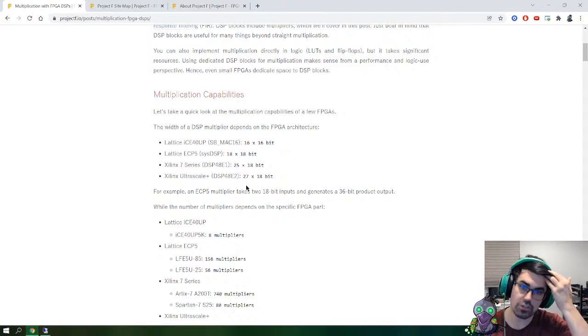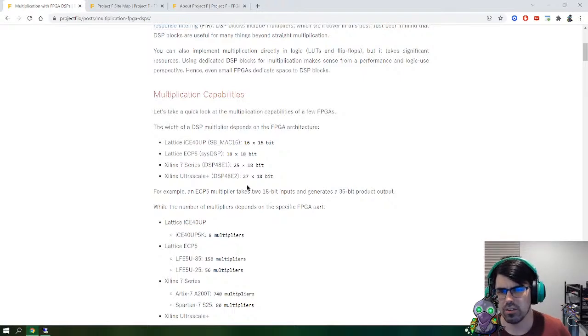Let's take a look at multiplication with different sizes. This is kind of interesting, because I was talking to a professor from Europe, I think, who was designing an 18-bit processor for the Series 7 FPGA, so it fit exactly with the DSPs. That's an idea: designing our HDL to match the capability of the FPGA. We can design a processor that's the exact width of a DSP, which can help achieve better performance and utilization while keeping sufficient accuracy in our algorithm.